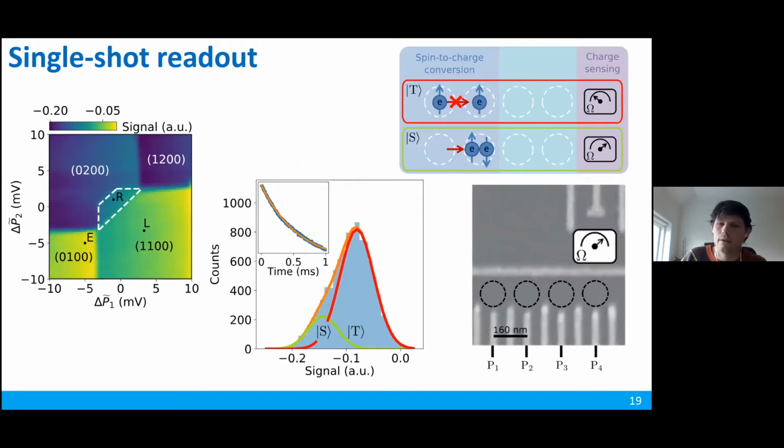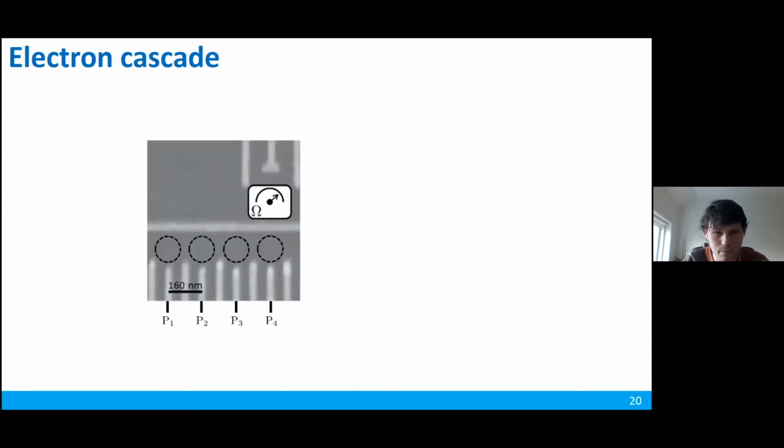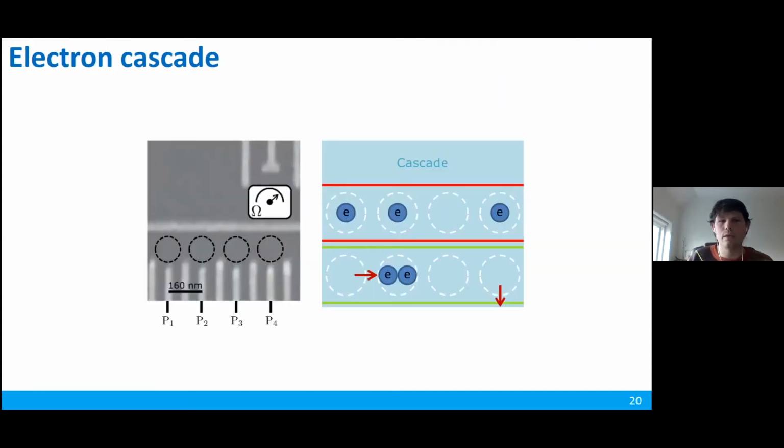So yeah, and as you of course already noticed, there's actually space designed here for two additional quantum dots. So perhaps now we can use these to somehow achieve a better readout signal. Our idea is that we, again, still have the two electrons on the left two quantum dots, but additionally, we put an electron on the rightmost quantum dot, the one which is really close to the charge sensor. And again, this charge sensor, the sensing basically relies on Coulomb repulsion effects, so it really drops off strongly with